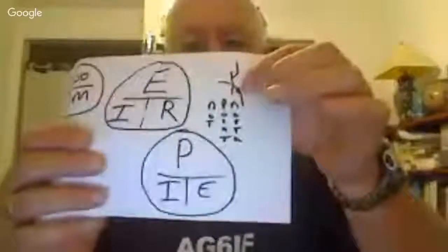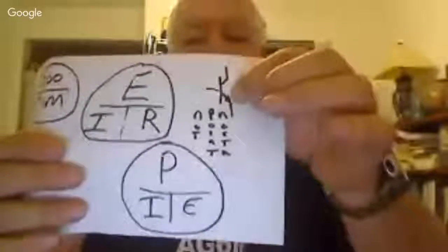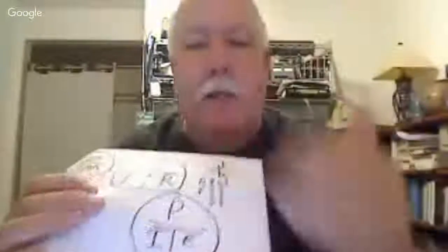There's another transistor that has a different makeup. It's called a PNP, and the arrow is pointing towards the body. So what's that one? Pointing north, probably. PNP. That's with the arrow pointing towards the body. And don't be fooled if they roll it upside down. Sometimes they roll them in different orientations, but that's typically the standard orientation right there. Makes sense? Transistor, a very, very important device.